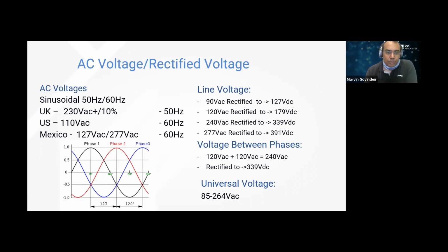And we also may have monophasic systems or three-phase systems. So the installation as well might give us access to live wires, a different number of phases and a neutral or just pure phases. And we have to tap off those lines. So when we take those voltages, we normally have to rectify them for a lot of applications. So we'll rectify those and we'll get a DC voltage out of that. So that could be, 90 volts rectifies to 127. It could be 240 rectifying to 340.